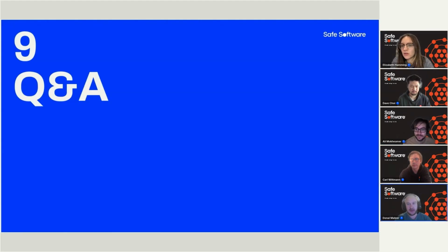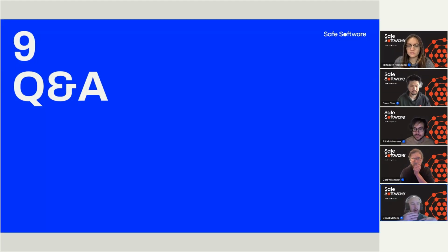Awesome. Okay. I was just going to cover some general questions as well. We often come across how to remove black backgrounds after reprojecting. The best way to do that would be through the RasterBandNodataSetter or remover. And also the difference between Tiler and RasterTiler. You can use both on raster data, but the RasterTiler will give you more contextual attribution. They're common imagery fundamentals and questions that will pop up.